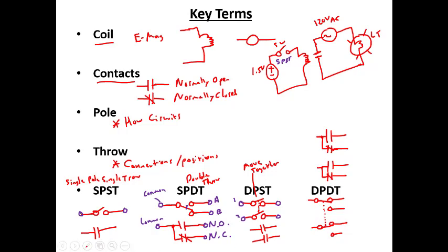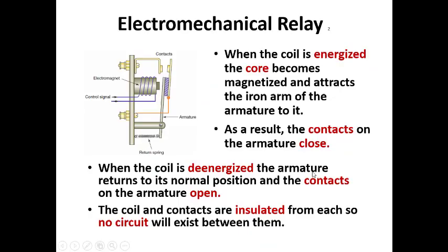And so if we looked at the pins, or where we would connect wires, we'd have screws here for the double pole single throw, and then for this one we would have wires like this. And this is the type of relay contacts that we're going to see when we get to our 8-pin relays later. They'll have two sets of contacts, both with a normally open and a normally closed setup.